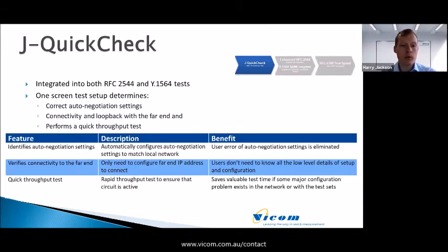it'll perform a very quick throughput test at the maximum rate that the test set is capable of for that given option. So even if you've got a 100 gigabit capable test set, if you've chosen the 1 gigabit test, it'll do a quick throughput test at 1 gigabit per second, even if the committed information rate you're going to be testing at is 200 megabits per second, just to test the serviceability of the line and to test the serviceability of the loopback device.